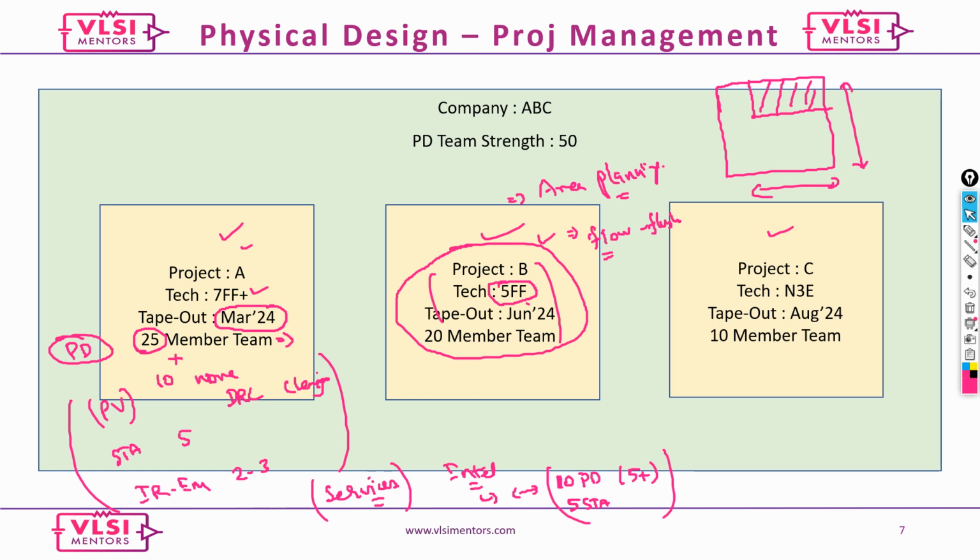And then ensure the flow runs smooth. So remember this, when you go from one technology to another technology, the tools have different settings. So you have to internally set certain things, and then some versions, say you might be working on ICC 2 23, say service pack 1 or something like this, or here if it is Innovus, so 23.1.1, something like this. So the tool versions may be different when you want to target 5 nanometer. So you might have to pick a different tool version.